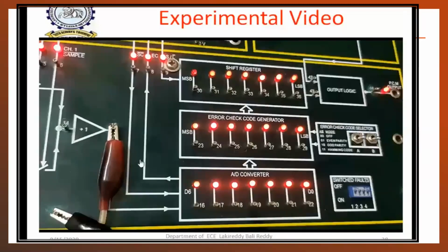Based on the number of samples, each sample value or each quantized value is encoded. That means initially at the first sampling time, one quantized value is passed. For that quantization, 7 bits of information are transmitted. That means for the first sample value or quantized value, a group of 7 bits is encoded. For the next sample or quantized value, again 7 bits are encoded.